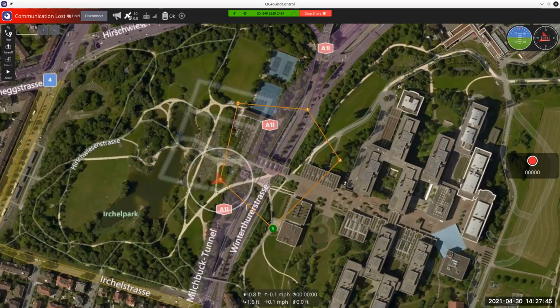And then finally, one other piece of information, which I find really useful with the students here, is Plot Juggler, which allows you to take multiple pieces of data that come from the log file of QGroundControl, and plot it to get an idea of what's happening with the guidance functions. You can see what's the commanded attitude versus what's the actual attitude, so you get some idea of the difference between the two.